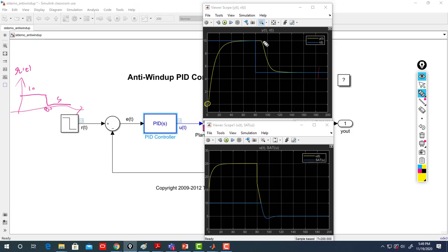So, this delay we also call the wind up effect, due to the saturation of your actuator. Each time your actuator saturates and you have an integrator, it means you have wind up effect, and this is due to the wind up effect. How to reduce it? Maybe for you this is not critical, so you don't implement anti-wind up in your physical system, because the saturation block means you are simulating the physical system. You can add friction, you can make it reflect reality more and more.